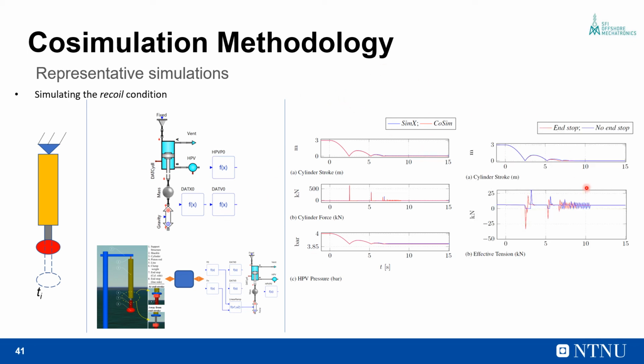We also demonstrate the effectiveness of the end-stop arrangement had the end-stop not been present, as shown by the blue line. The small segment of riser that is modeled in the OrcaFlex model would not go into compression when the cylinder hits end stroke. But with the end stops model, we see that as the cylinder hits end stroke, the riser element goes into compression. And so we see that overall there is satisfactory agreement between the pure multiphysical simulations and the co-simulation model developed.